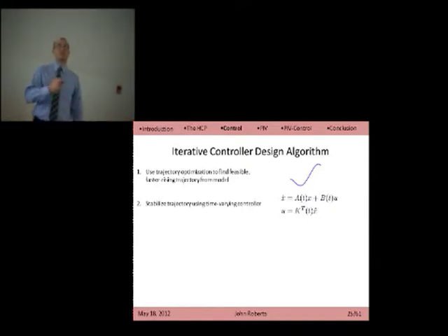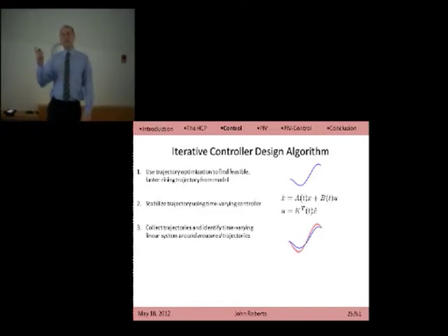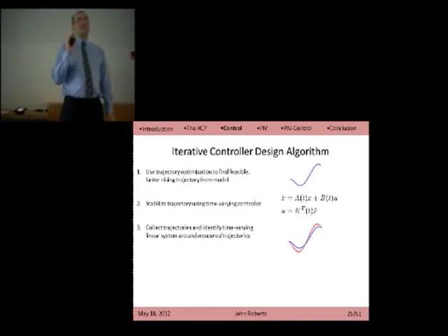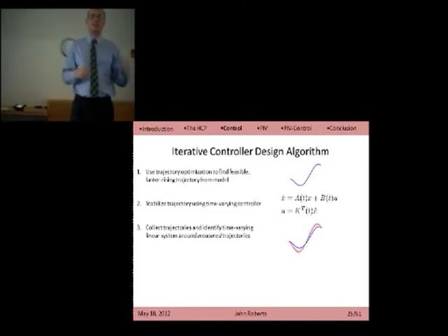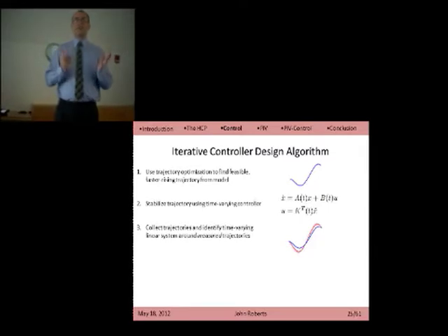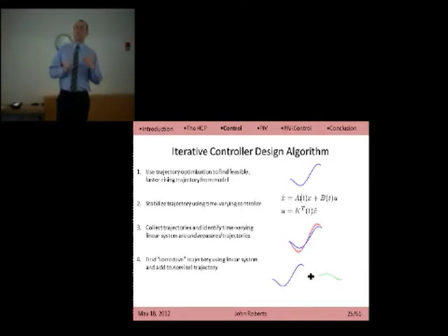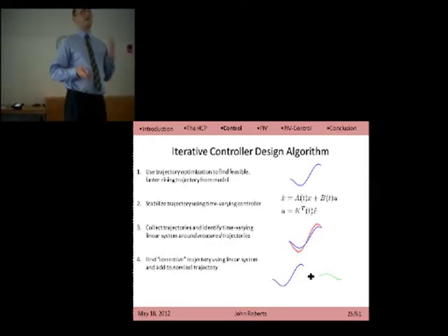So we collect all these trajectories, and around them we can fit a time-varying model that captures the behavior of the system near the captured data, not elsewhere, just near that data. And because that's a relatively small domain, even a simple linear model is enough to represent those dynamics. Then within that model, find a corrective trajectory. For example, something that reduces overshoot without increasing overshoot in another degree of freedom, without having too high velocities at the end, respects the requirements of the system, but locally improves it.